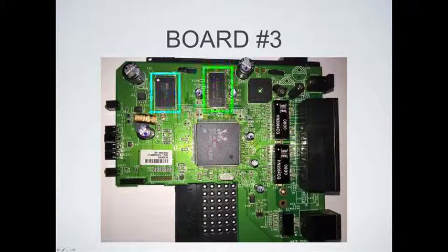So when we take those numbers and plug them into Google, do some searching, we find that the MX chip is also a Micronics chip. It's actually an MX29LV800CBTC, and that is an 8 megabit parallel flash. So that's another parallel chip versus a serial. These parallel chips are pretty big. They're almost as big as a RAM chip, so you have to pay attention a bit.